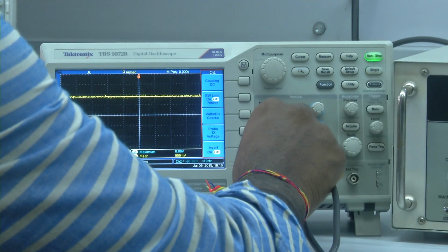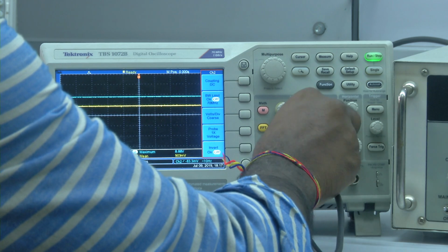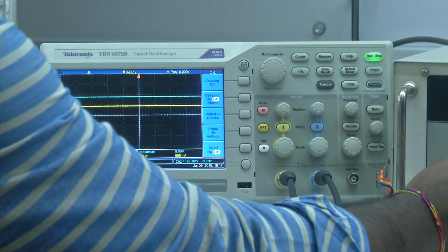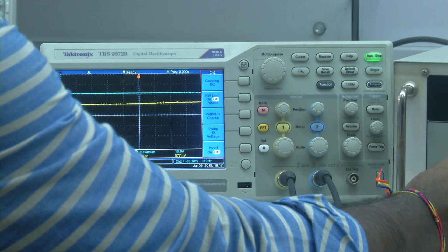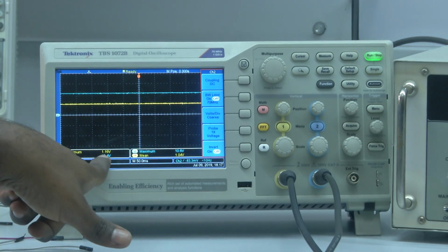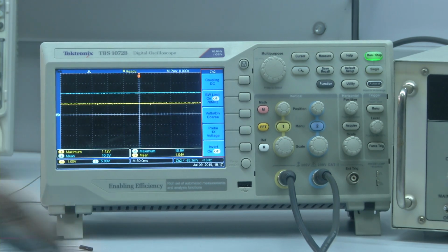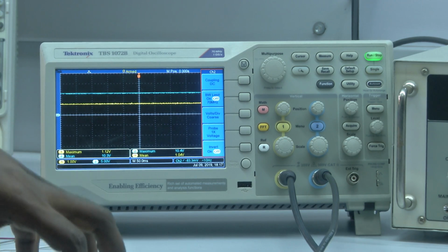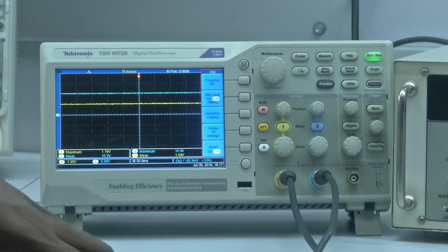I am also changing the scale of it, to a 5 volts scale. So, if you observe, the input applied is 1.04, and the output we are getting is 10.3 volts, which means that the gain is now 10 and the phase is also the same. So with this we can clearly see that we were able to design the gain of 10 amplifier using an inverting amplifier.